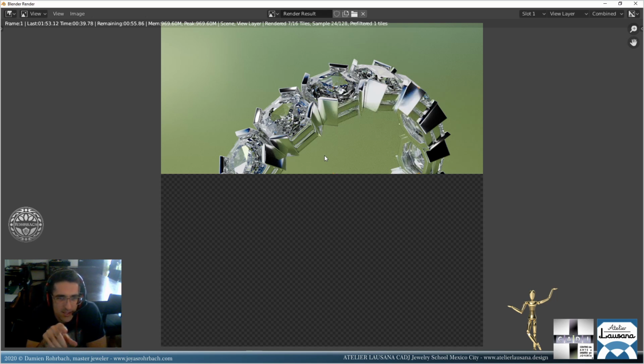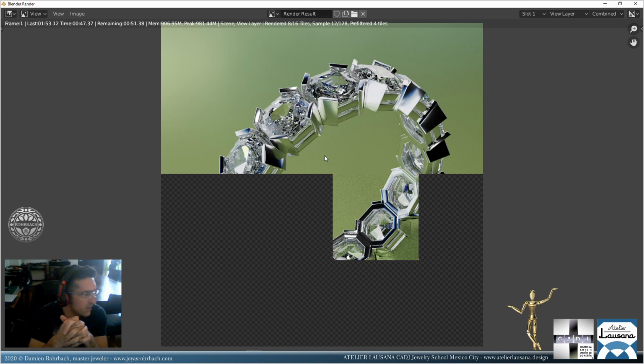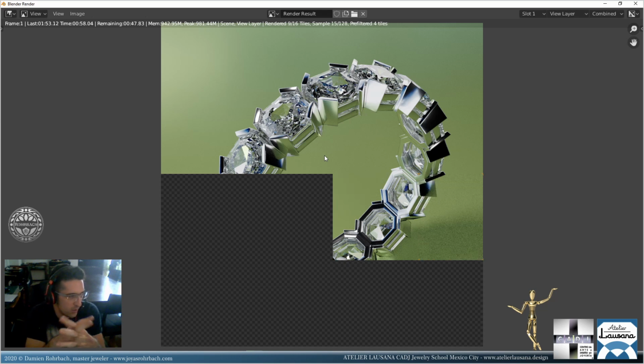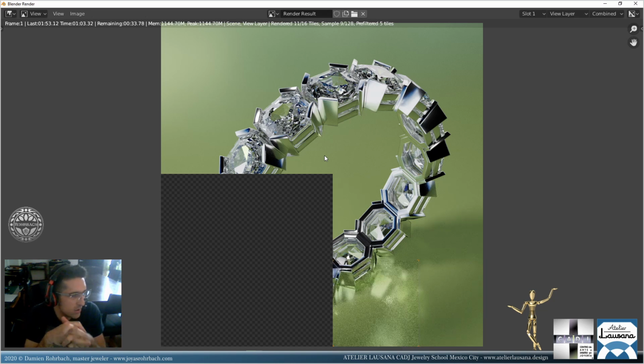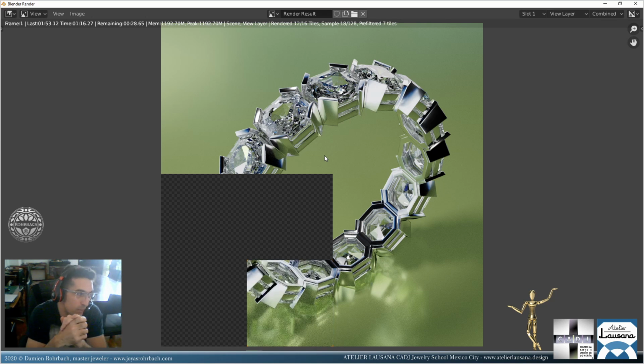And also for setting the stones, you can make the cuts using the boolean with the stone to make the cuts, the pre-cuts. Sometimes we do that in 3D. Inside the setting, we can make the cuts where the stone setter is going to work, so we can make the cut directly in the 3D model, so it comes out printed and it comes out in the production mold, and it's faster and it's better for the stone setter. But some stone setters don't like that.